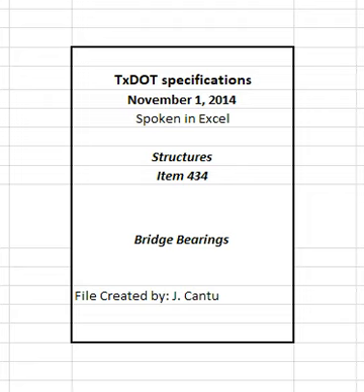1.1 Elastomeric bridge bearings. Plain elastomeric bearings, consisting of elastomer only. Laminated elastomeric bearings, consisting of alternating individual layers of elastomer and steel laminates, with or without a steel top plate and special components, steel guide bars and bottom plate.